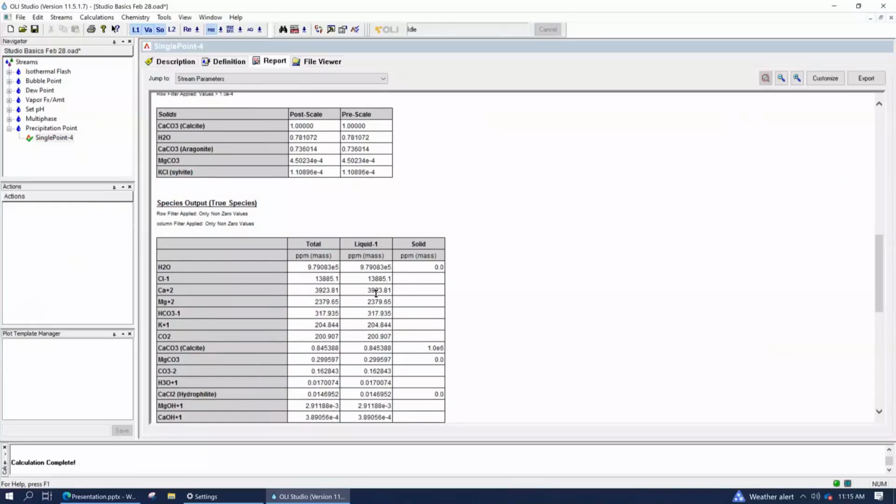So AJ, one designates in this table, scale tendency, one designates the threshold at which scale is thermodynamically stable. Is that okay? Exactly what it is. And anything else that means it did not quite get there, still has not formed anything, it did not precipitate to anything. That's right. Anything that's less than 1 means that the system is subsaturated with respect to it.